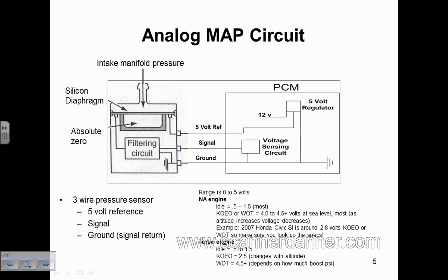And one of the quick checks, let me give you a couple. Turn the key on, engine's cold, look at ECT and IAT. They should be what? Should be the same. Car's been sitting overnight, you have the scan tool connected to the car. You're doing a drivability issue on an unknown vehicle. You've never worked on it before, but it doesn't matter. These are some fundamentals you want to adopt. Look at ECT and IAT on the scanner.